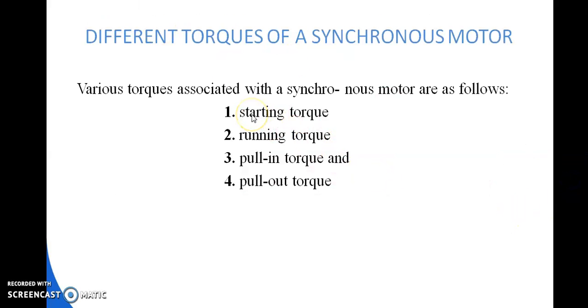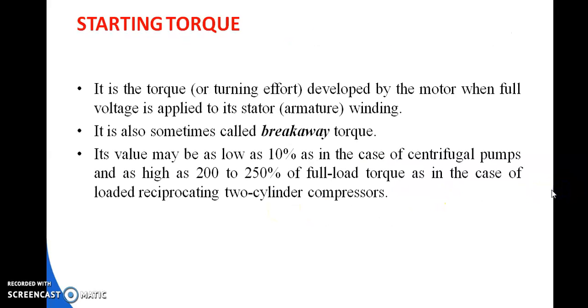Here we will see different torques of a synchronous motor. Various torques associated with a synchronous motor are as follows. First one is starting torque, then comes running torque, third one is pull-in torque, and the fourth one is pull-out torque. First one is your starting torque.